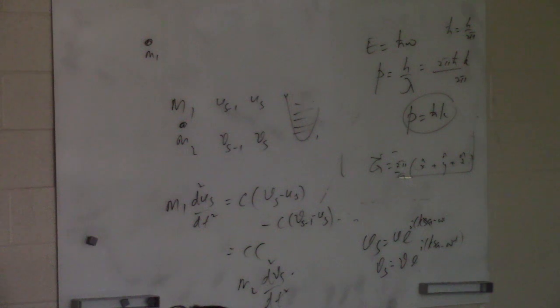Can you imagine? This is a material, right? If it's a finite material, phonons can always get scattered from the boundaries. If the phonons are moving this way, they can get scattered from the boundaries of the sample. Or if you have, say, a polycrystalline sample, what are these? Grain boundaries, right? So these phonons can get scattered from the grain boundaries. So grain boundaries are very important places where they can get scattered.